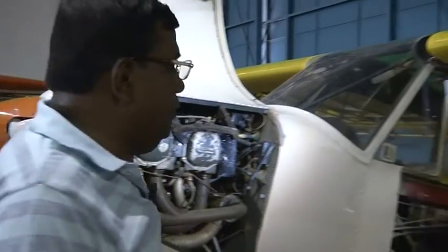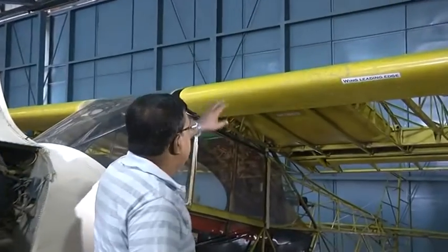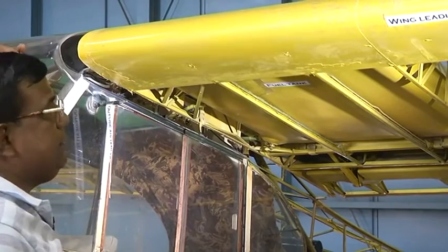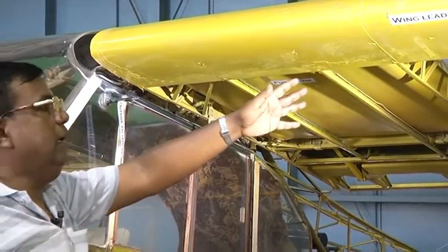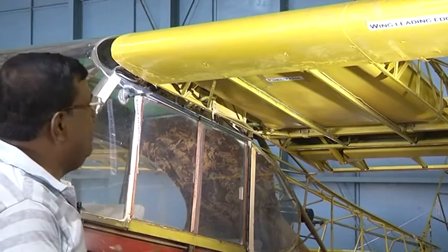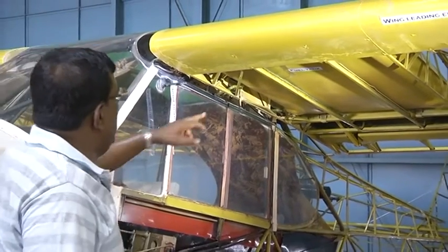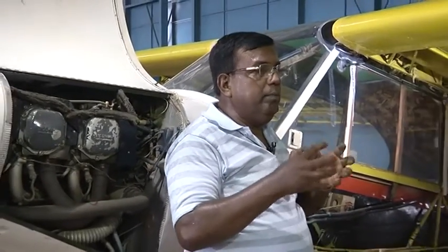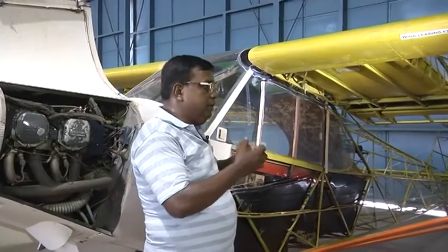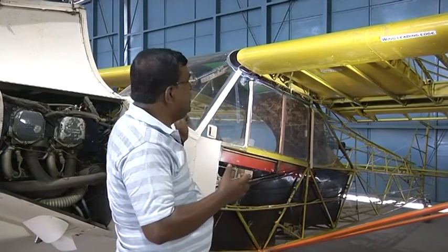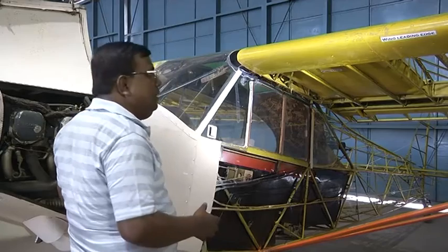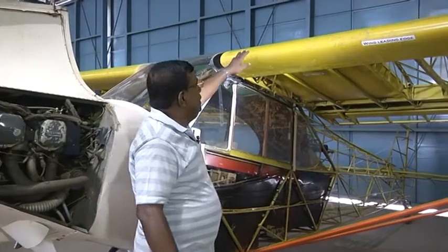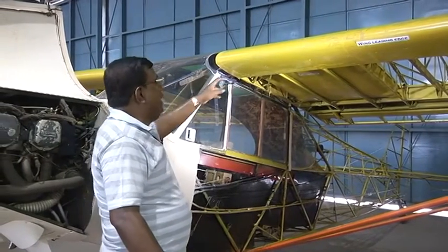If you look at most aircraft, you will find the fuel tank is in the wing. Here is the fuel tank. You could see here, one fuel tank here, one fuel tank that side. For a larger aircraft, there could be a larger number of fuel tanks. The most important part, please understand, is that fuel has to go to the engine, and the engine has a driving pump, and that pump is used to pull the fuel and put it inside the engine. So all engines will have their own driving pump, which we call the driving fuel pump. And since it's a high wing, the fuel from here to the engine comes by simple gravity drop.